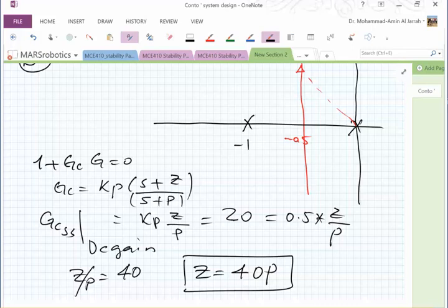If you select P 0.01 times 40, it is 0.4, right? Even for this case, this is too large. So we can select P to be 0.001. So if I select P 0.001, so this is design, right? You tell me why you selected P, because I want to make the angle contribution at the desired location minimum. And if you come and tell me, okay, I want to select 0.0001, I'll tell you no problem. Go ahead.